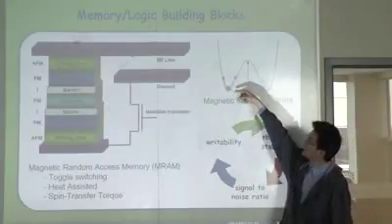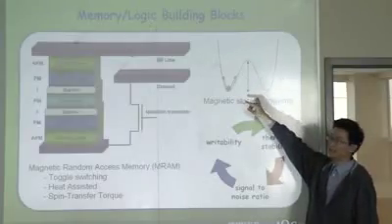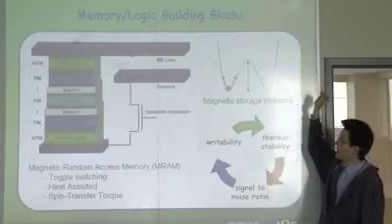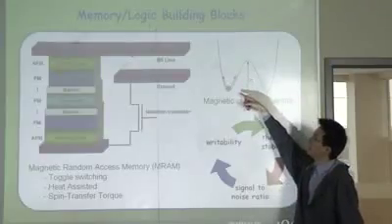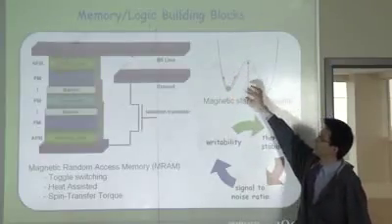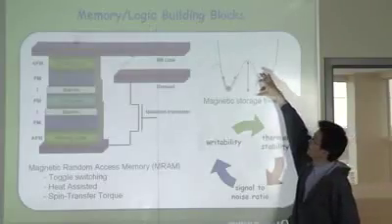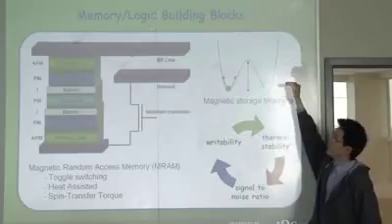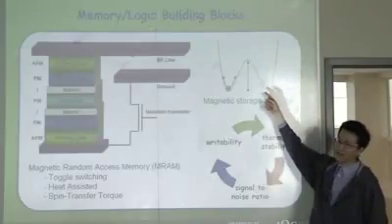The main problem is that in magnetic recording, you have two stable states, which we call the 0 and 1 states. They are separated by an energy barrier. If the temperature of the system is so high, the state of the system will reverse, and then you lose your data. We can increase the energy barrier to prevent that from happening, but then you run into the writing problem.